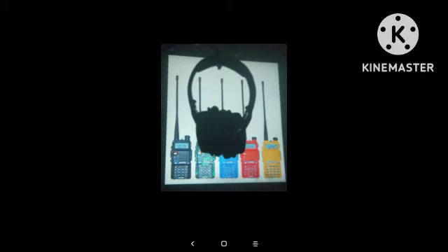34. When a parallel coil capacitor combination is supplied with AC of different frequencies, there will be one frequency where the impedance will be the highest. This is the resonant frequency. 35. Resonance is an electrical property used to describe the frequency characteristic of a coil and capacitor circuit.